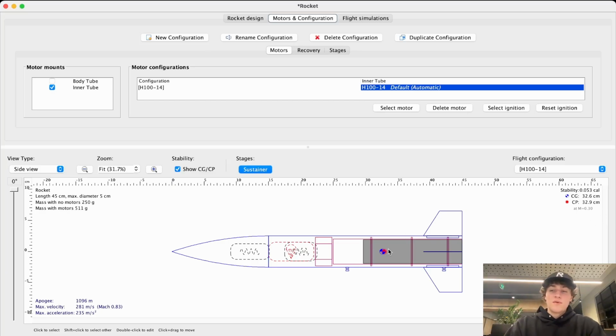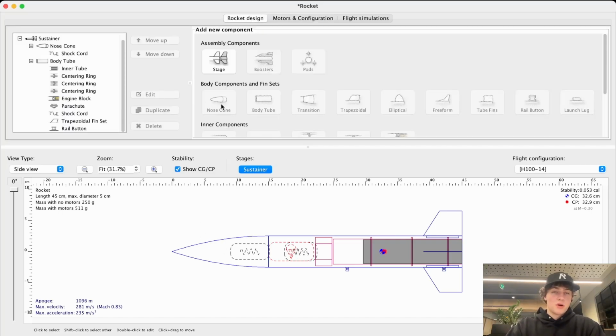So if we want to move our center of gravity further along the rocket, one pretty typical way to do that is to add mass to our nose cone. Because this is a center of mass, the further away we add the mass, the greater the torque. We'll be adjusting the CG by a greater margin. So we'll typically put it right in the end of the nose cone, so that we don't have to add as much weight and we can still move the CG a ton.